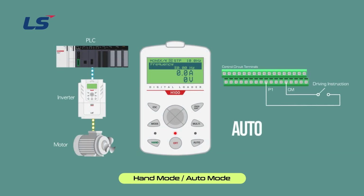Auto mode can control the inverter through communication. The inverter operates according to the command source and frequency reference source set in each of DRV 6 and 7. If the driving command is set to on, the inverter starts operation as soon as the auto key is pressed. You can see that the command frequency source changes at the top of the keypad.